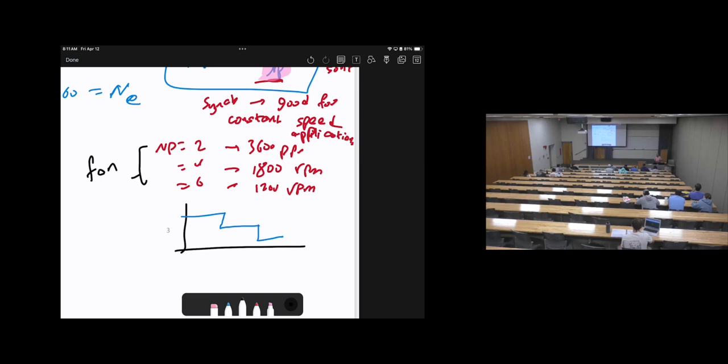We started finding a way to control the frequency going to the motor. This means we can control the speed by changing the frequency, by adding a power electronics device. So, as a result, when we have power electronics that can control the frequency, then we can control the speed. That's why, right now in electric vehicles, you will see a lot of synchronous motors. And they are modifying the synchronous motor by adding permanent magnets; it's called the permanent magnet synchronous motor, PMSM.